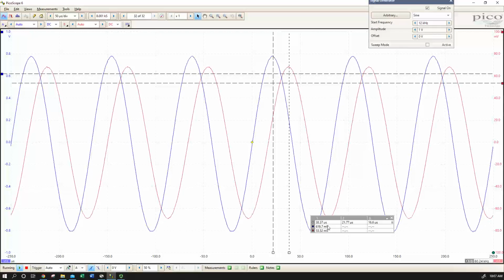So using our oscilloscope, using a pure resistor in series with our resonant tank, our inductor capacitor resonance series couple, we've been able to demonstrate that our as measured resonance frequency is very close, is within component tolerance error, very likely of our calculated resonance.